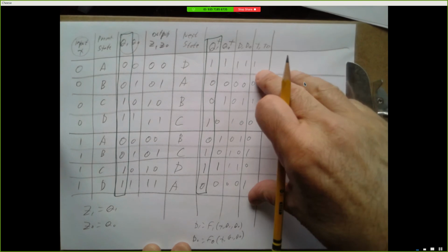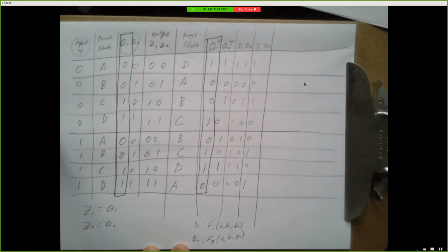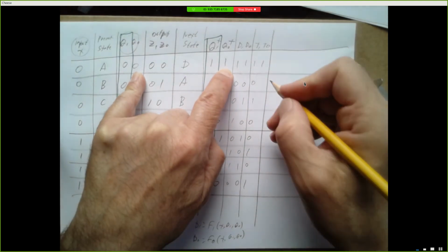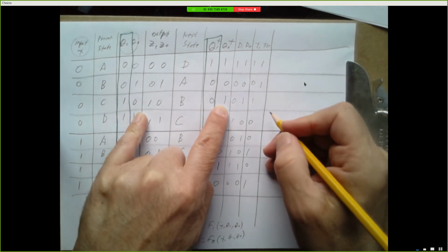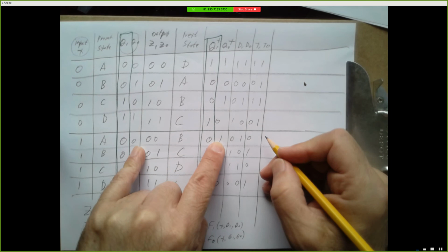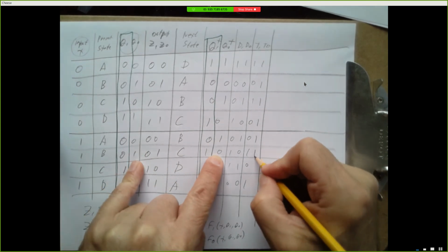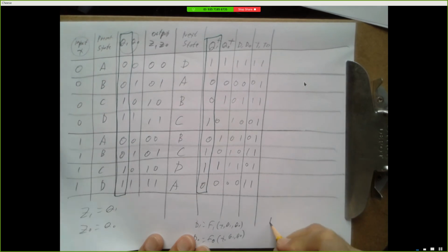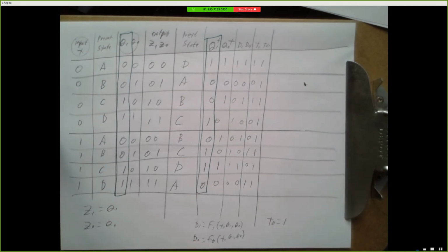And this is a pretty succinct equation when you put it in the K-map. It'll come out a little simpler than the D1 input. Okay, T0, I'm looking at Q0 and Q0 plus. I'm going from a 0 to a 1, toggle. Going from 1 to a 0, toggle. 0 to 1, toggle. 1 to 0, toggle. 0 to 1, 1 to 0, 0 to 1, 1 to 0. Guess what? My equation for T0 is really simple. I just tie it to 5 volts.